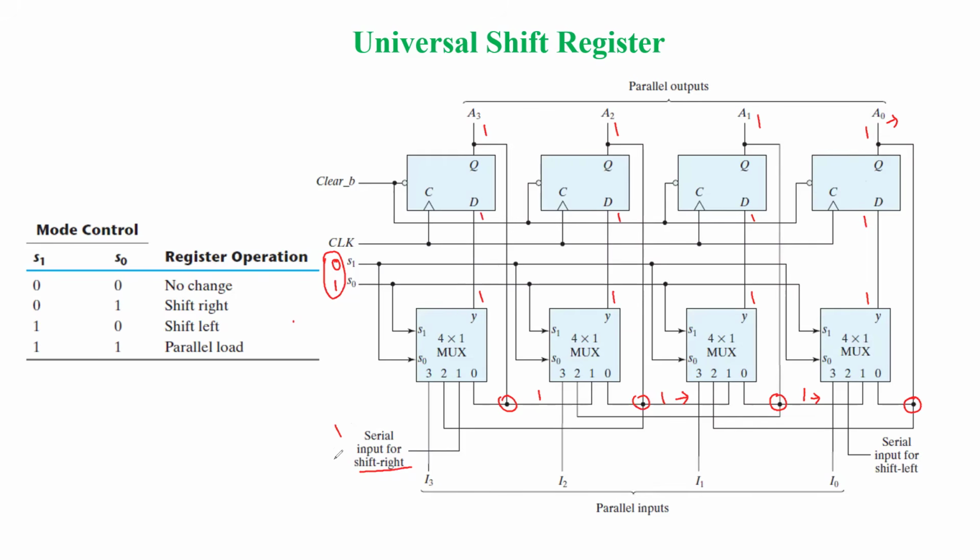In that way also we can observe, and this is going to work as serial in and parallel out also. Parallelly we are able to get the output from here. So when it is going to work as serial in serial out, at the end of the fourth clock pulse or after the fifth clock pulse, we'll get the first LSB output here from the rightmost flip-flop.